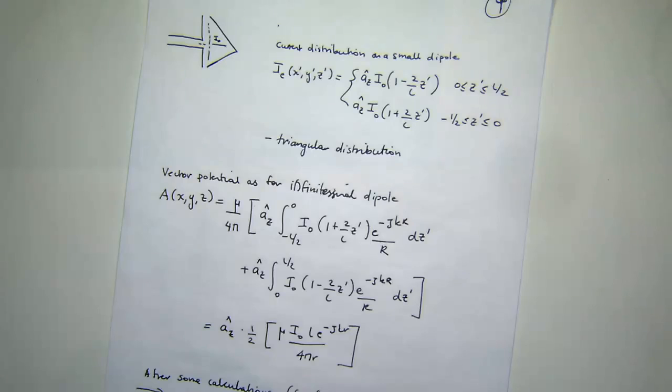That's right. So if you're matching it up to 50 ohms and essentially the radiation resistance of a dipole is 0.3 of an ohm, what it means is a very small amount of the incident power is actually radiated. Okay? And we also went through the directivity and the radiation pattern.